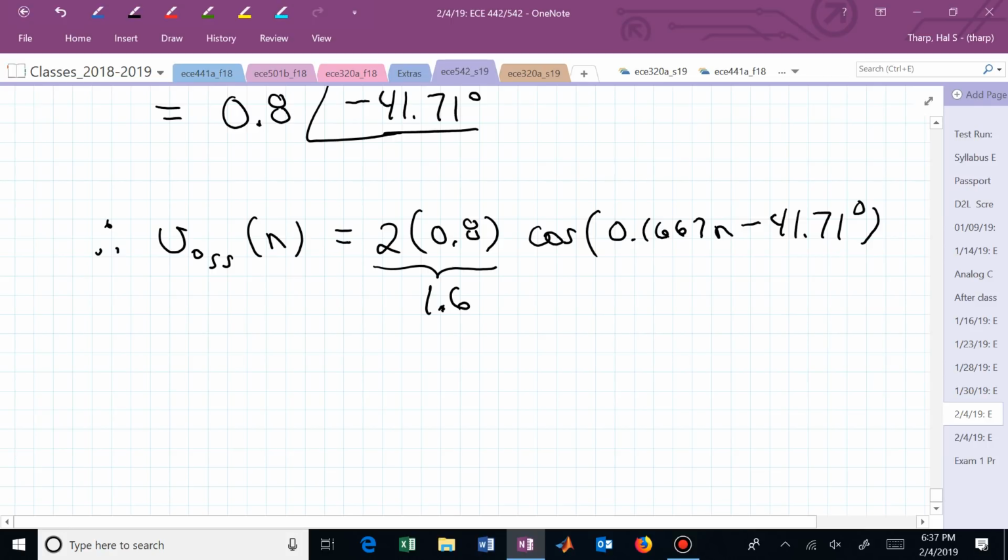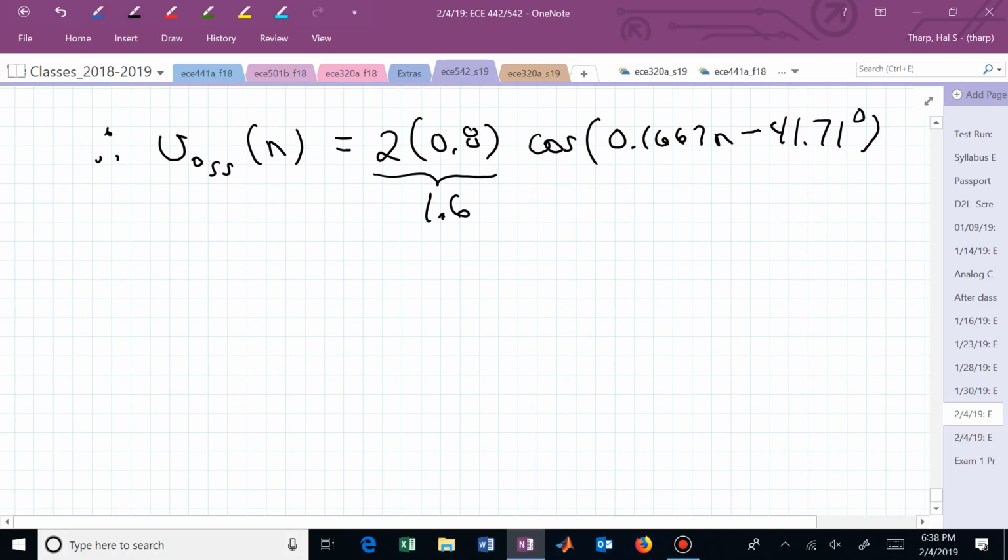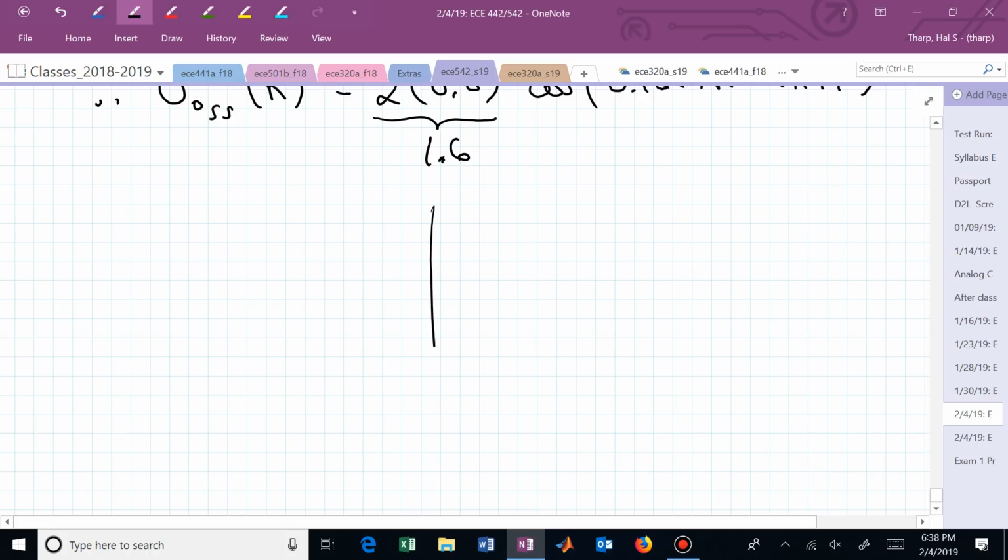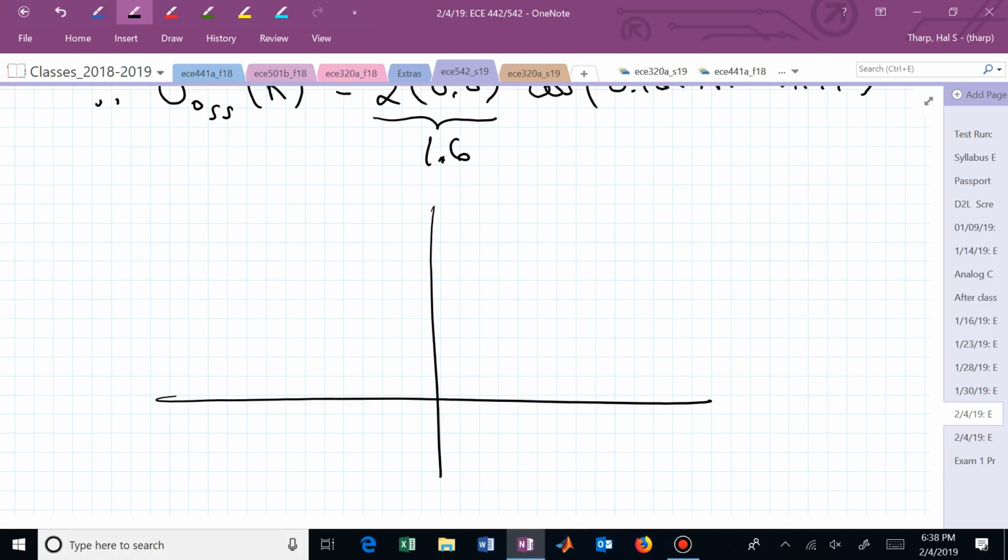And that's now our sinusoidal steady state output based on passing this cosine through a first order low pass filter with a bandwidth of about 100 hertz. And hopefully you can see then that if you needed to, you could have pulled out your napkin and measured this all with a ruler and a protractor, because you had, here's 1 and here's 0.8, and here's that point.